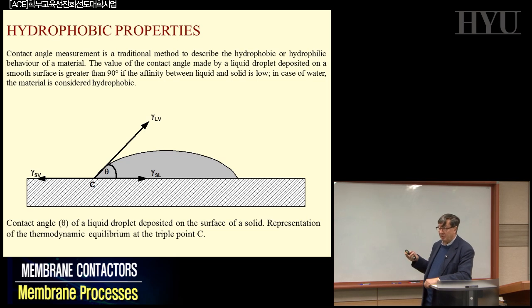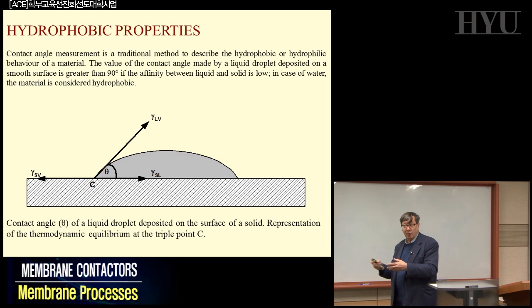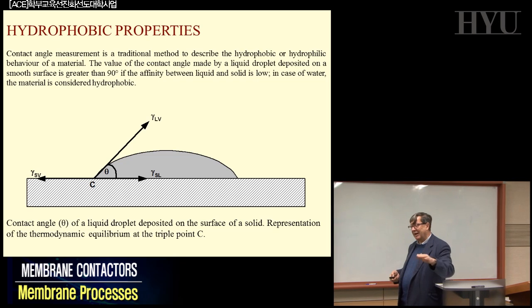If you induce some hydrophobic character by, for example, plasma deposition, by attaching some fluoropolymers, which are typical hydrophobic materials, you always have to check the lifetime of this hydrophobic character, because you can have what is called a recoil phenomenon. You can have a nice hydrophobic character for 5 hours, 5 days, 1 month, but slowly this hydrophobic character disappears.